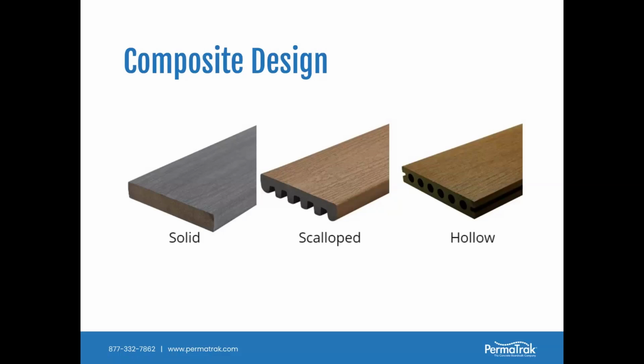For the specific manufacturer, and like I said, Trex is one of them, the capacities of these materials are going to be listed by the manufacturer, because the components of what goes into the exact fiberglass product are specific to the manufacturer. So only the manufacturer would be able to tell you how to design or what those capacities are. So those become a matter of pulling load capacities from a chart by the manufacturer.